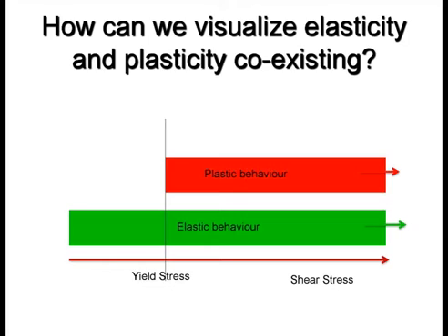So even though the line has crossed the family of plastic potentials, there's no plastic behavior over here. So that part is irrelevant. Only when you hit the yield stress is the plastic behavior activated. At that point, it looks for the family of plastic potentials. You got an idea? Okay. So this is how it worked out. I hope it gives you a very detailed idea of how that model actually works.